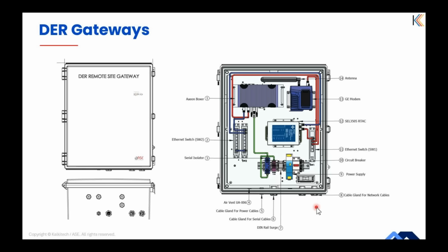So essentially, this gateway receives the operational commands like the hourly limits from FlexConnect sent via the AC aggregator. It then interfaces with the customer's energy management systems or directly with the controllable assets, collects critical performance data from these assets, and ensures the site responds correctly as per the utility requirement. So this robust integrated hardware is a cornerstone of ASC's offerings, providing the reliable on-site intelligence and communication needed for demanding grid interaction programs.